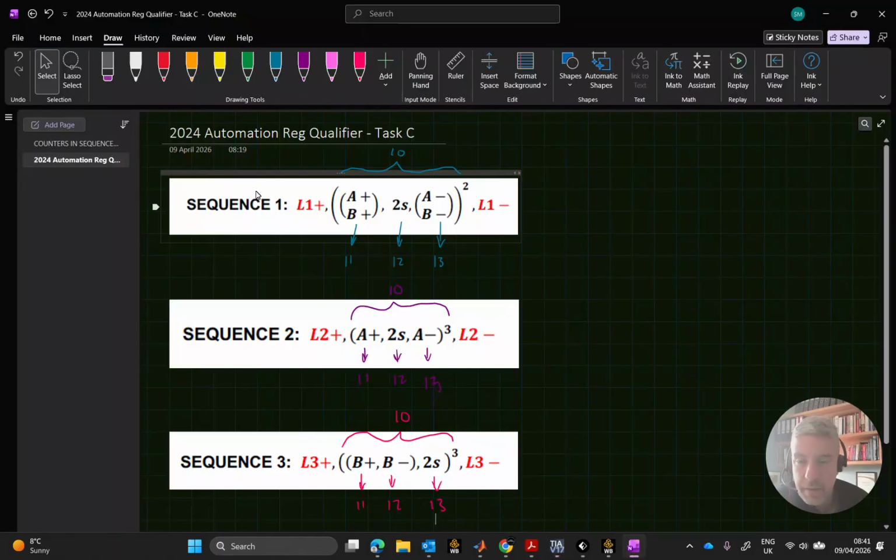All right. Now, in my sequence 1, I need to look after my counters. So in each of the 3 sequences, my check step is step 10. This is the step where I take the decision to say I should be going into the counter function or moving past it. So I'm in step 10, so this is going to be 10. And my increment step in each of these cases is going to be 13. So the increment means you accumulate on the registration of another count when you're on step 13.